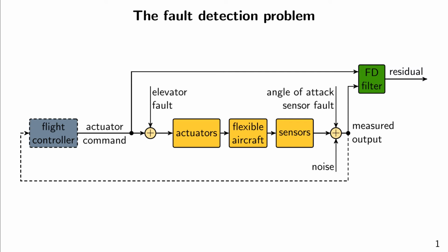Hence, in this talk we explore the limits of using a rigid model when designing a fault detection system for a flexible aircraft. We do this by synthesizing an array of filters with different bandwidths for both models and calculating the smallest detectable fault and detection time as a function of the bandwidth. Using this data, we establish the performance thresholds below which a rigid model is sufficient.